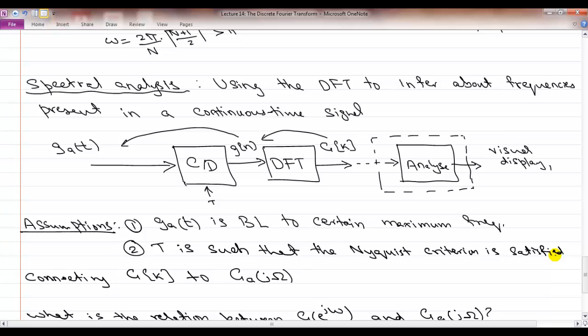Take the example of the spectrum analyzer: eventually you have to say, I have collected enough samples, I'm going to stop collecting samples and do an FFT on those samples. That is a process called windowing. We are going to limit our sequence. That creates some imperfections called spectral leakage. You get frequencies where they are not present, and the frequencies where they are present sort of lose their sharpness. We won't go into the details. I just want to bring that to your attention. You should be aware of those concepts.